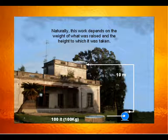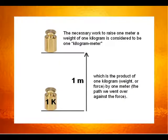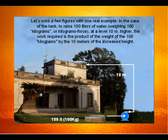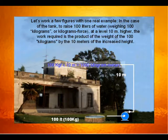The necessary work, to raise 1 meter a weight of 1 kilogram, is considered a kilogram meter, which is the product of 1 kilogram, weight, or force, by 1 meter, the path we went over against the force. Let's work a few figures with one real example. In the case of the tank, to raise 100 liters of water, weighing 100 kilograms, or kilograms force, to a level 10 meters higher, the work required is the product of the weight of the 100 kilograms by the 10 meters of the increased height.